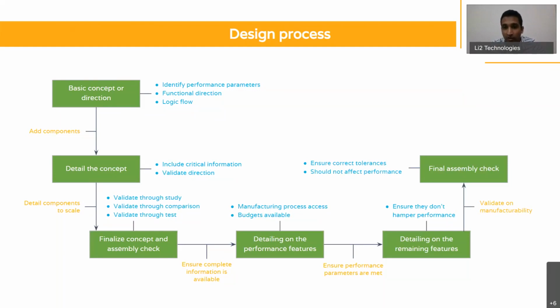If you want a transition fit, you give a transition fit. If you want a clearance fit, you give a clearance fit. So you have to make sure that these aspects are met in your design. It is not a wise way to work where you allow this decision to be taken by the manufacturer. You as a designer should ensure that under any condition of manufacturing, these aspects of your assembly are met and they shouldn't affect the performance.